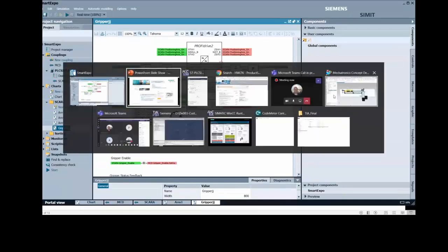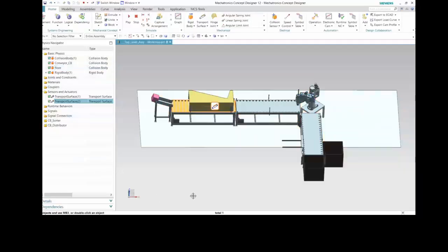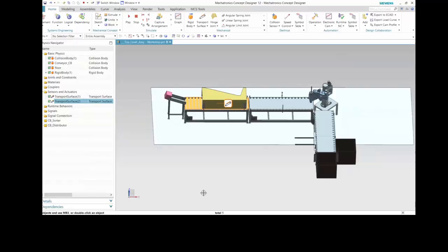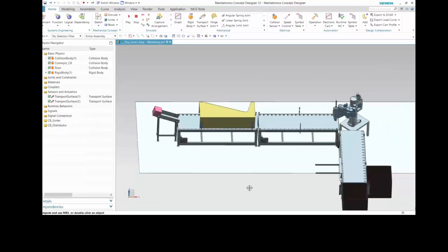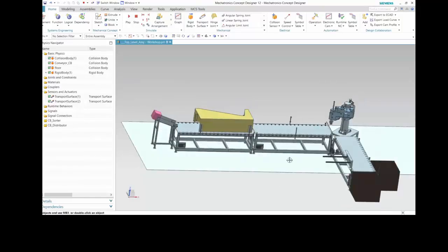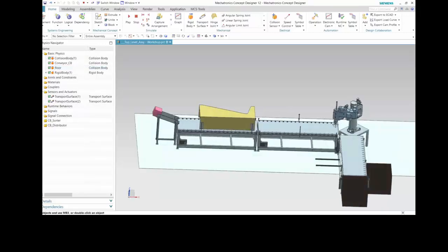Before I do that, what we're going to see now in the live demo, we have these 3 conveyors. All these 3 conveyors are controlled by my code, which is written in TIA Portal. And based on the positions of the box, they activate different sensors. And these sensors then turn the conveyors on or off. And we have 2 different sizes of the box. One is a short box, one is a taller box. So they pass through these sensors here, and depending on whether it's a short box or a taller box, the SCARA arm would do the pick and place motion. Once they come down this conveyor, there's a sorter arm. So again, depending on the size of the box, they are sorted either in this box or in this box.